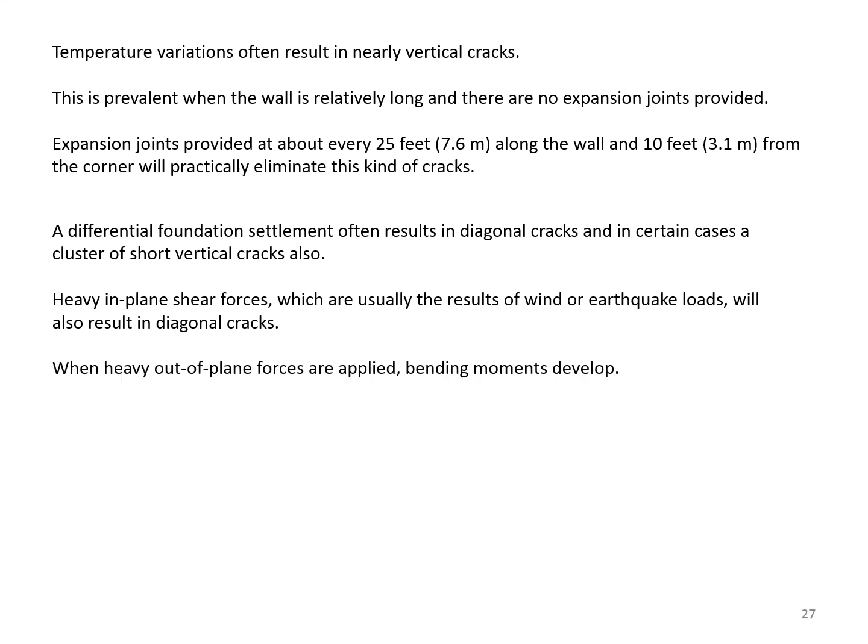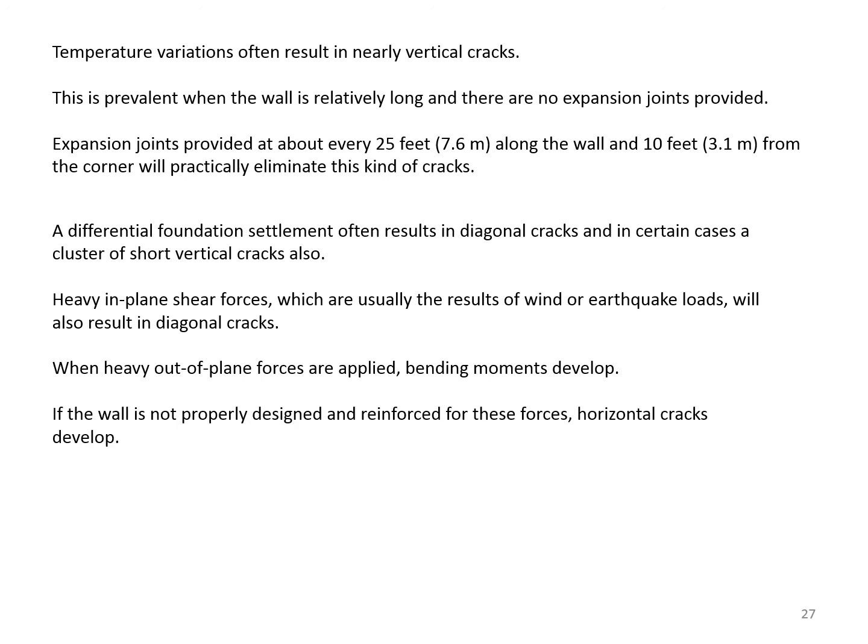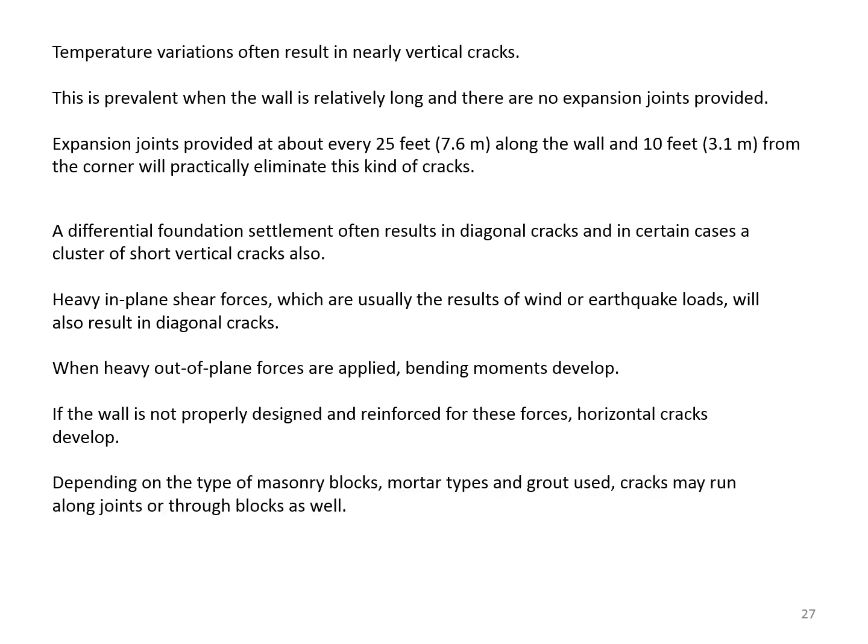When heavy out-of-plane forces are applied, bending moments develop. If the wall is not properly designed and reinforced for these forces, horizontal cracks may develop. Depending on the type of masonry blocks, mortar types, and grout used, cracks may run along joints or through blocks as well.